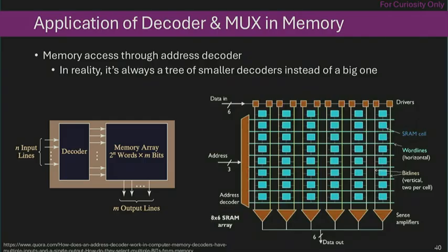The benefit of having a single 1 within that 8 bits is a really convenient way to make a selection within 8 different components. But you see our memory nowadays is a lot larger, right? They have like 32 or 64-bit addresses. So we typically have multiple levels of decoders to handle this decoding process. Having a single decoder for a 64-bit address is just too much. You cannot accommodate 2 to the 64 different output ports.